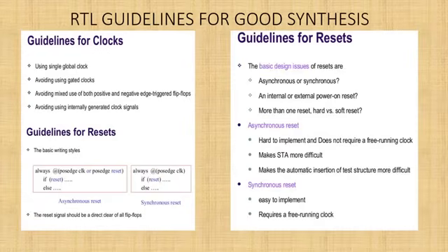The RTL guidelines for good synthesis for a clock is the clock should be global. It should not be gated clocks. We should avoid as much as possible the mixing of both positive and negative edge triggered flip-flops. And we should also avoid using internal gated clock signals.